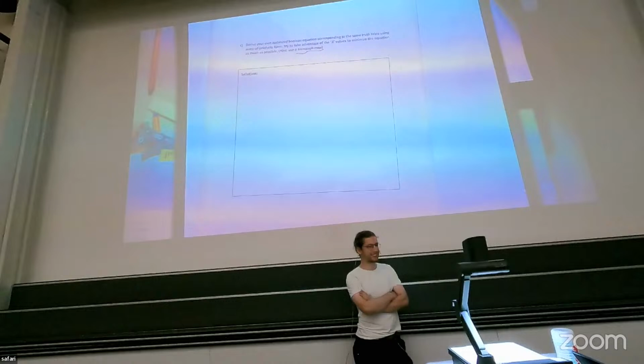Okay, let's make it very simple. If I need a 64-bit memory, I could do the following. I could take the 32 bits from here, and 32 bits from here. The address 8-bit goes here, the address 8-bit goes here. The data in 63 to 32 comes in here. The data in 31 to 0 comes in here. There you go.